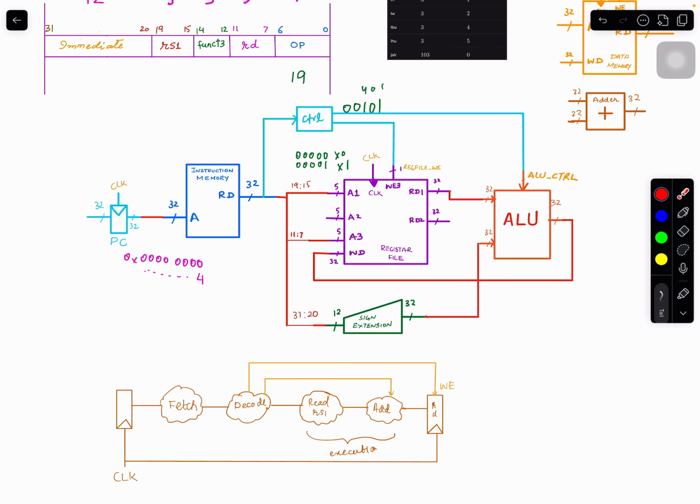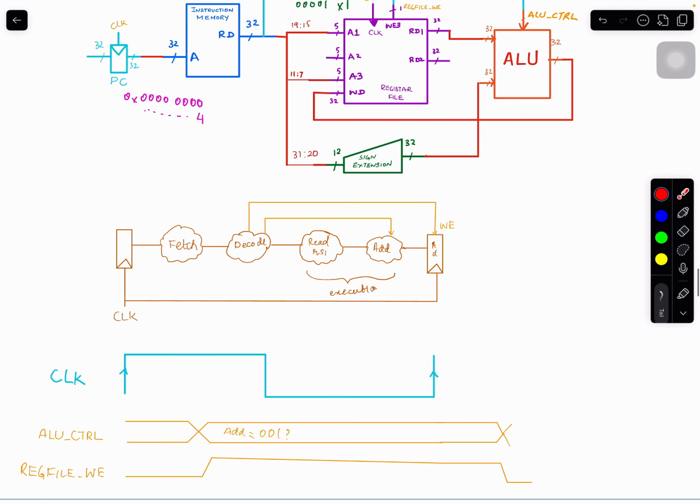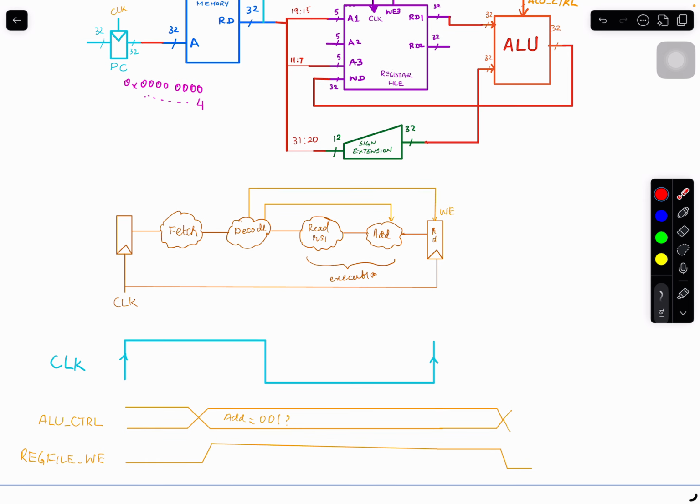And when the next clock edge comes, so on this edge we came here, next clock edge comes, we are ready to move the input here to the output of this register, or we can say we are now updating the value of this register. Make sense? After the rise edge, we do fetch and we do execute sometime around here. This is not a time diagram, okay? We're just showing different things happening. This is more like an action.